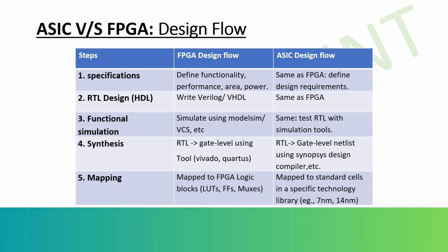So now we will quickly see FPGA versus ASIC, basically a summary table. FPGA is a reconfigurable hardware chip, however ASIC is a custom built silicon chip. The cost for FPGA is high per unit but there is no fabrication cost. So overall you can say the FPGA implementation is very cheap. However, in case of ASIC it is very expensive.